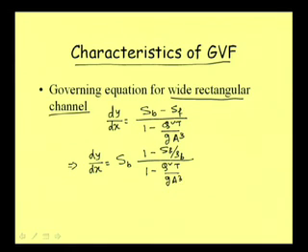Now, these two terms, SF by SB and this Q square T by G A cube, we can express in terms of normal depth and the depth of flow at any section, and this term we can define in terms of critical depth and the depth of flow of gradually varied flow. So, let us just try to do that first. Well, for a wide rectangular channel, we know that, well, if we do not remember, let us just refresh that part.